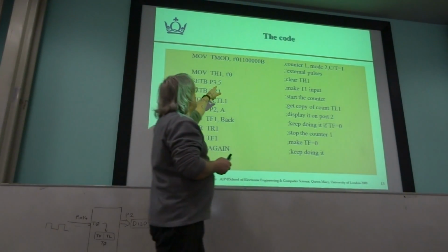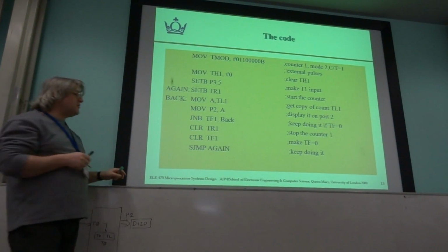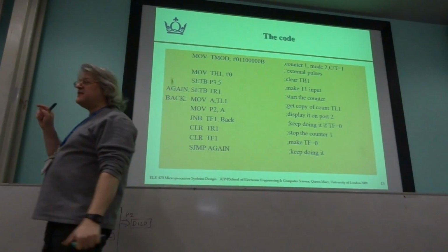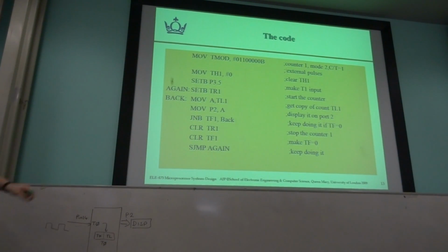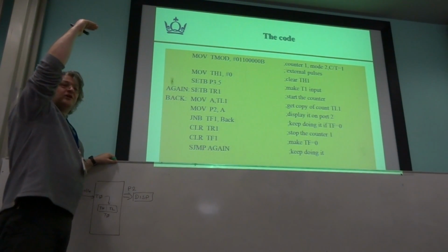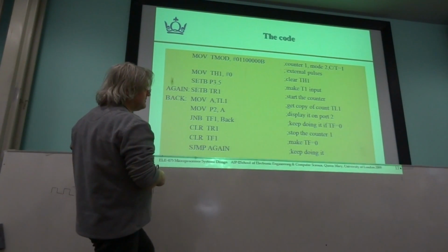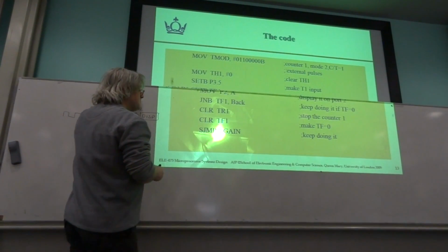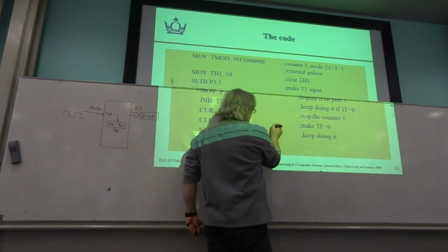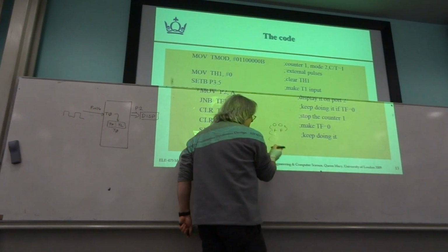If you wanted to count, for example, 16 packages before doing a reload, what you would do here is take 16 away from 0, if you like. You don't write the number 16 because it will count from 16 all the way up until it overflows. So if you want to count blocks of 16 packages, effectively you're basically saying, well, it'll overflow when it goes from FF to 0. You've got to work back 16 steps from that point.